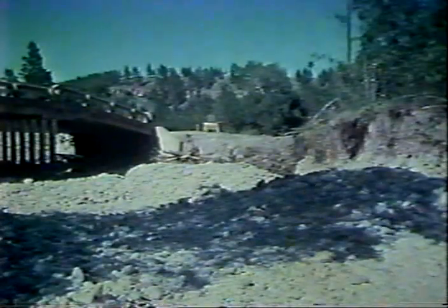This bridge on Spearfish Canyon in the Black Hills of South Dakota provides an example of lateral erosion, in which the stream breached the road embankment adjacent to the abutment. In this example, lateral migration of the channel has overtaken a pier that was originally on the floodplain, exposing the footings and support piling. This problem is most common on large streams, for which the capacity for lateral migration is easily underestimated.